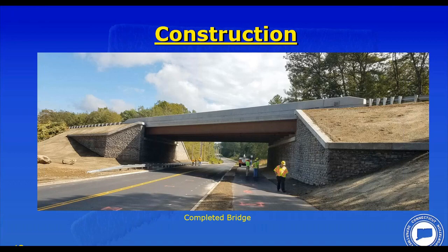Connecticut does build quite a few steel bridges. We actually aim to get about 50% steel, 50% precast or pre-stressed concrete. This particular bridge made sense to go to steel. So it's a weathering steel bridge. With GRS IBS, we have no approach slabs, we have no bearings, we have no joints in the bridge. It's a simple saw and seal joint at the top. No approach slabs, which definitely reduces cost. So these are very cost-effective structures.